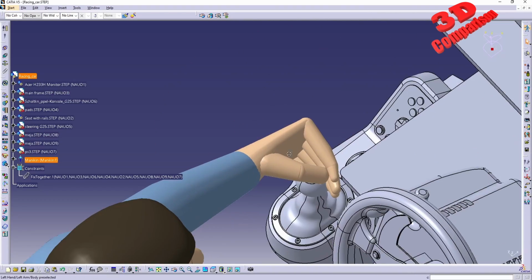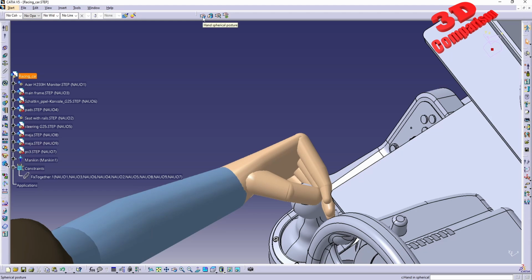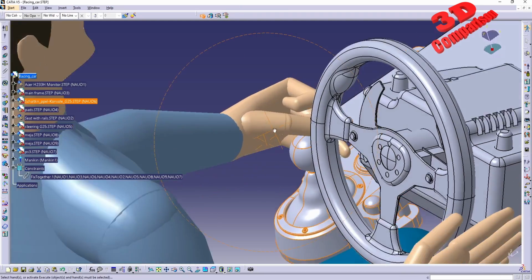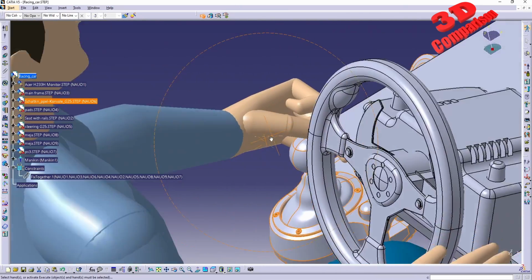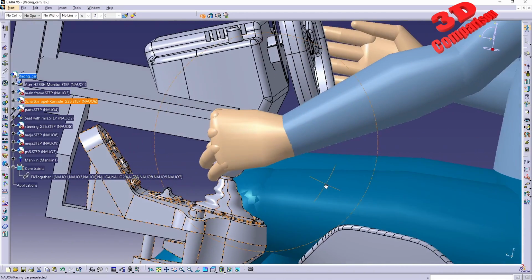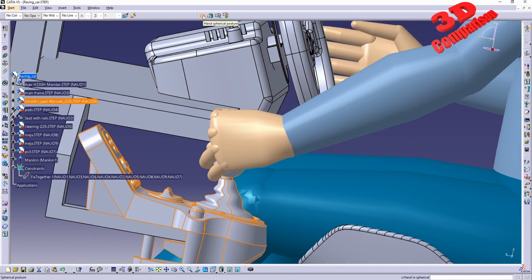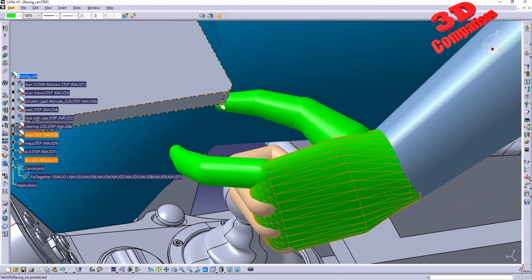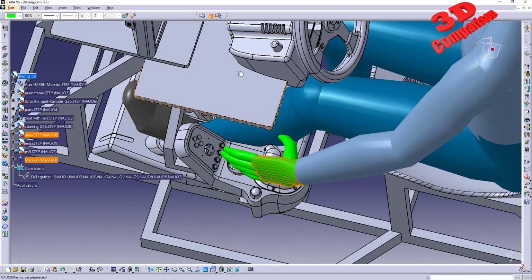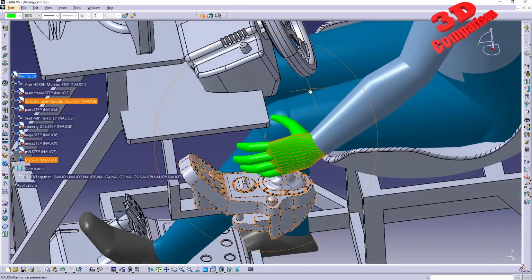And over here we see the position of the hand, and I will go for a spherical hand posture. Select the hand and do an auto compute, and we're going to see how that will process. So even though the shape over here is not individually spherical, the mannequin will go into a spherical hand position just by selecting those. So this will be pinch. As we can see, for pinch, those two fingers will be used. This will be a cylindrical posture, and this will be the spherical posture.